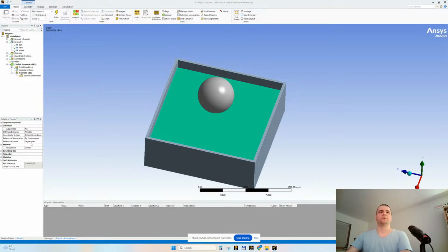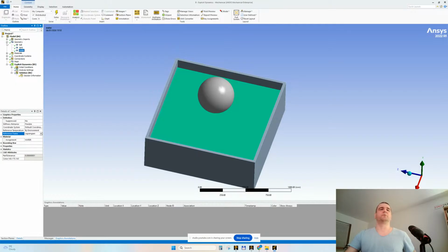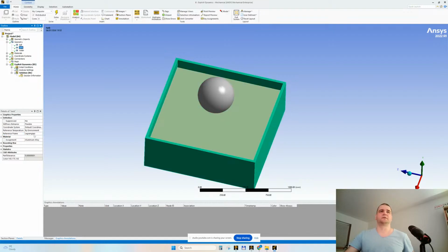Water, and we are leaving default here, reference frame Lagrangian, all right? This is default, because in the future, we will change it to Eulerian, and let's also change it to particle in a few minutes. All right, let's leave it default. This is a beginner simulation, with beginner errors. All right, this is an error. Having water Lagrangian. Having Lagrangian frames for these is just normal. They are solid bodies, solid parts. Their structure. Okay.